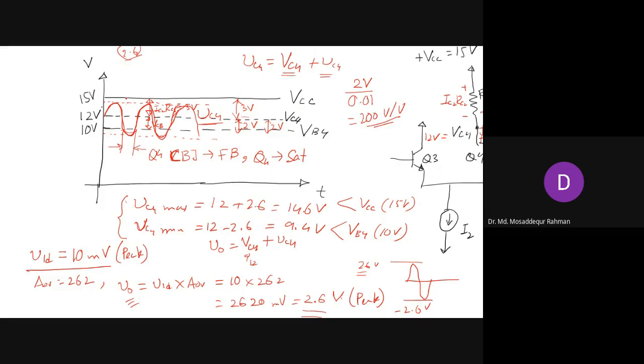So we have VC, IC, RC3. Then we also should have 3 volt of difference here. If you can set VCB at 3 volt, the collector base voltage 3 volt, then the signal will be able to swing in both directions. It will be able to swing a maximum of 3 volt, and of course 2.6 is also within that limit.